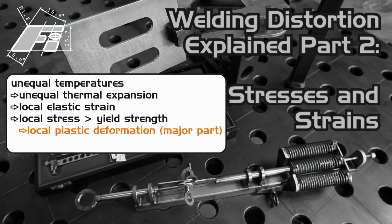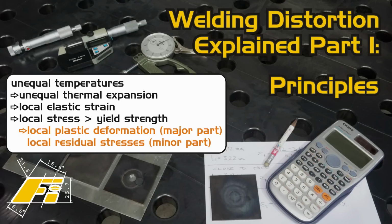The minor part of welding distortion is caused by residual stresses, which the workpiece is subjected to after cooling. The latter part may be only a fraction of the total distortion, but it can lead to additional springing back distortion with subsequent machining or heat treatments of the workpiece. But even if the welded component is put into operation right after welding, residual stresses pose a certain problem.